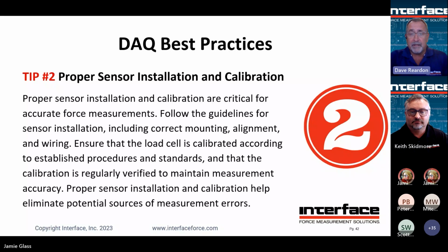The cabling and the wiring is extremely important. Again, this is reiterated many times throughout the presentation. The size of the wires, the length of the wires, the longer the cable run is, typically you need to have a larger gauge wire to assure that you're not getting a lot of temperature drift within the system.